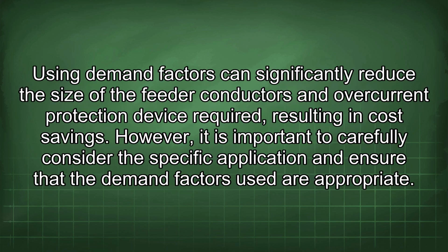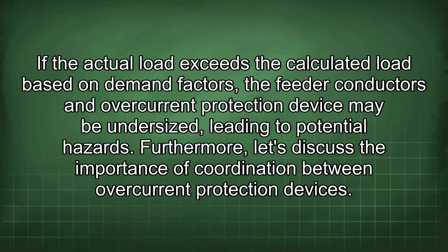Using demand factors can significantly reduce the size of the feeder conductors and overcurrent protection device required, resulting in cost savings. However, it is important to carefully consider the specific application and ensure that the demand factors used are appropriate. If the actual load exceeds the calculated load based on demand factors, the feeder conductors and overcurrent protection device may be undersized, leading to potential hazards.